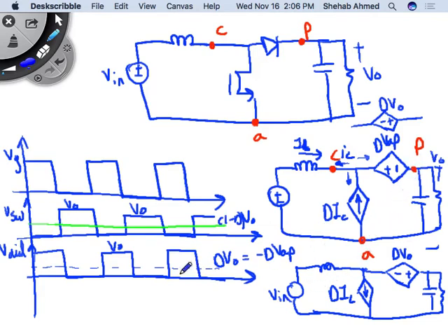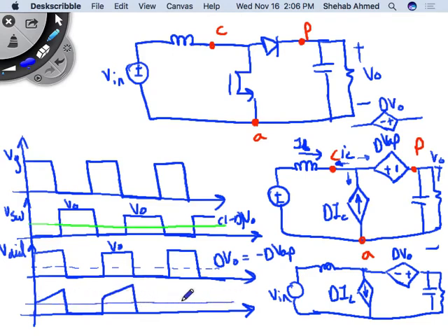Okay, and then let's draw also the switch current. When the switch is on, there will be current, and this will have an average value. Same, it's equal to D times IL, which is the opposite of D times IC, if IC is the current that's flowing here. We're okay with this? So now, does all of this make sense or not? This may be a little confusing, but let's see if it boils down to the same thing that we've been deriving before, okay?